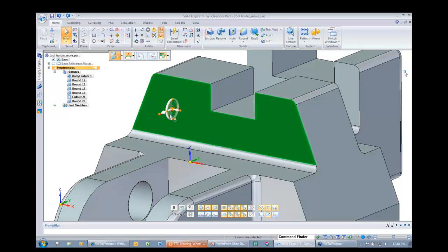But if I come back here and I do the Shift left click inside the tool plane again, now it's lying down. If I hold down Shift and left click on the origin, I've let go of my Shift key and my left mouse button. Notice how wherever I move it around, it's going to maintain that orientation. So I can come up and dock it on that corner point, and it won't try to snap to the edge. That's a nice tip and trick that I use quite often.